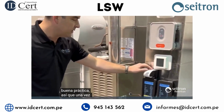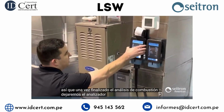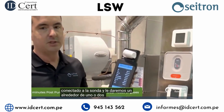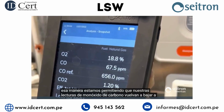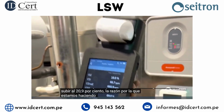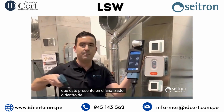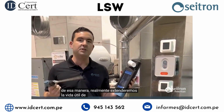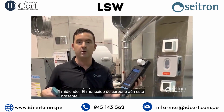So once the combustion analysis is over, we're going to leave the analyzer connected to the probe and give it about 1 to 2 minutes to purge, all right? That way, we're allowing our carbon monoxide readings to drop back down to 0. We're letting our oxygen go back up to 20.9%. The reason why we're doing this is we want to make sure that any of that residual carbon monoxide that's present in the analyzer or within the sample line is fully purged. That way, we're going to really extend the lifespan of our CO sensor because when we turn it off, it's not going to still be measuring carbon monoxide that's still present within the instrument.